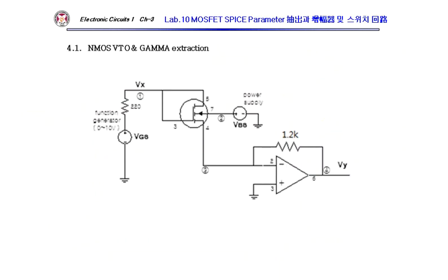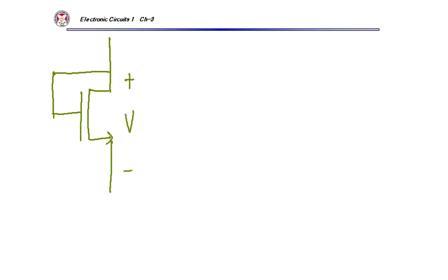Okay, let's go back to the circuit. This is a MOS, and I am skipping the bulk node. If I put it like that, and then this voltage is some V, drain and gate are connected together. My threshold voltage is positive. It's called an enhancement MOSFET.